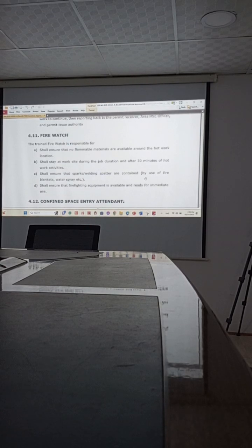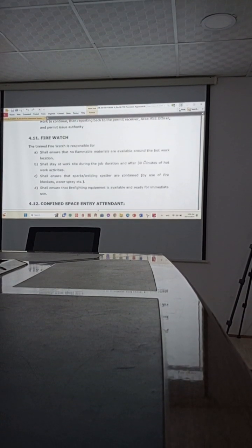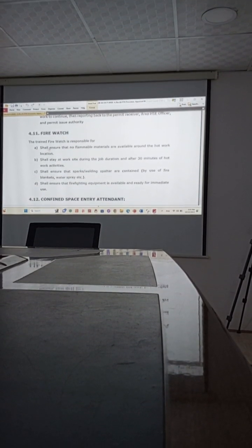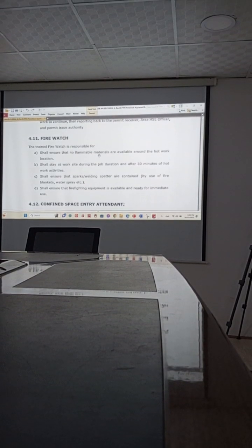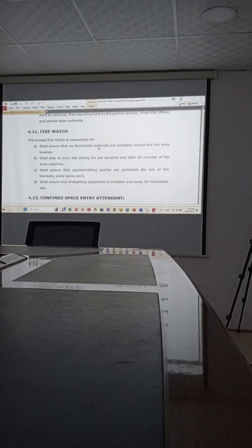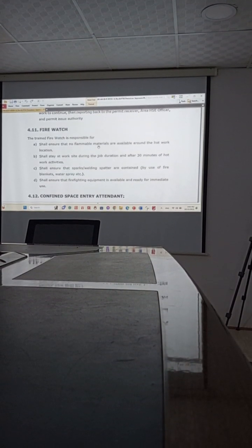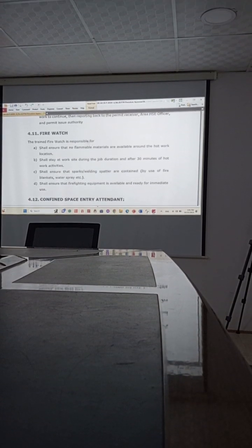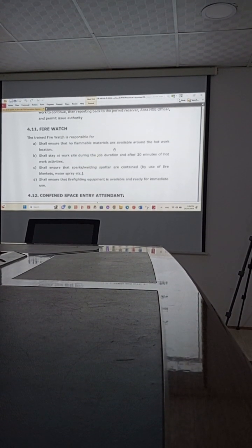Firewatch, 30 minutes. The firewatch shall ensure no flammables. This is the activity of the firewatch, but you need to understand it as a permit receiver, because you are requiring the firewatch. How many minutes does the firewatch need to stay? 30. Why?